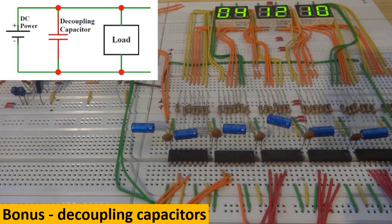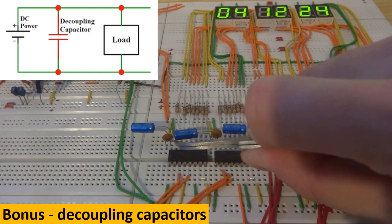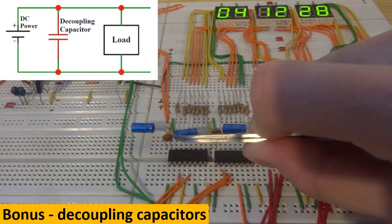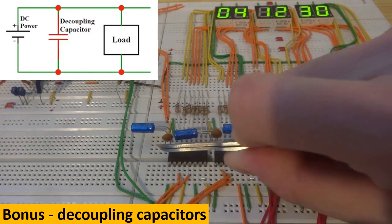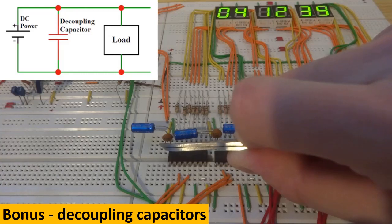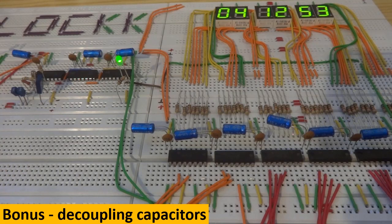This capacitor reduces the noise on the power supply line. So one node of the capacitor is connected to plus 5 volts, as close to the chip as possible, and the second node of the capacitor is connected to the ground. Usually we use 100 nanofarads.